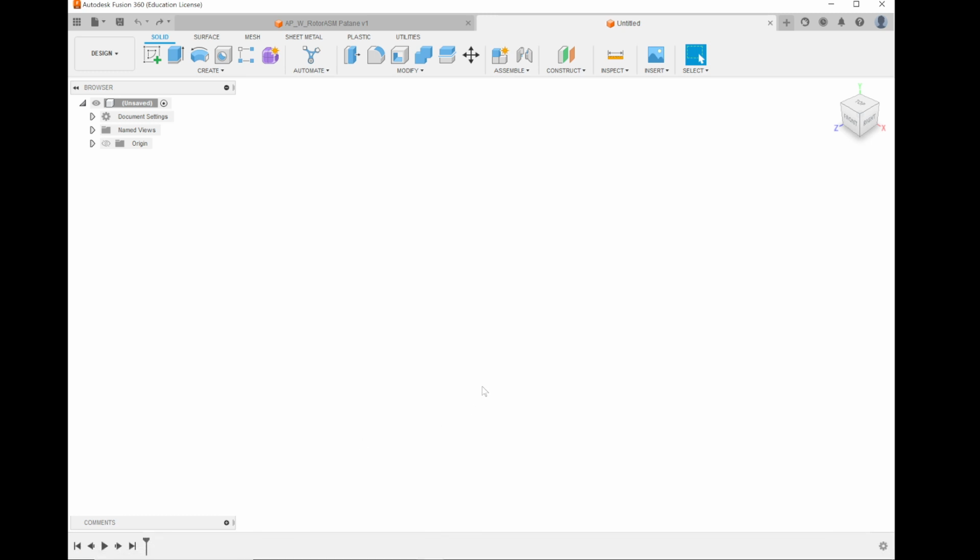So let's actually start making a shape. Fusion is an additive maker, so we're going to start by making a 2D shape. This is called a sketch. Please make sure you're in the Design tab over here. You want to be in the Design tab, and up at the top, you want to make sure you have Solid selected. If you have Surface or Mesh, you'll see they're different colors that we don't use. I'm not going to teach you with those because they're not useful to us. We're going to make sure we're in the Solid realm.